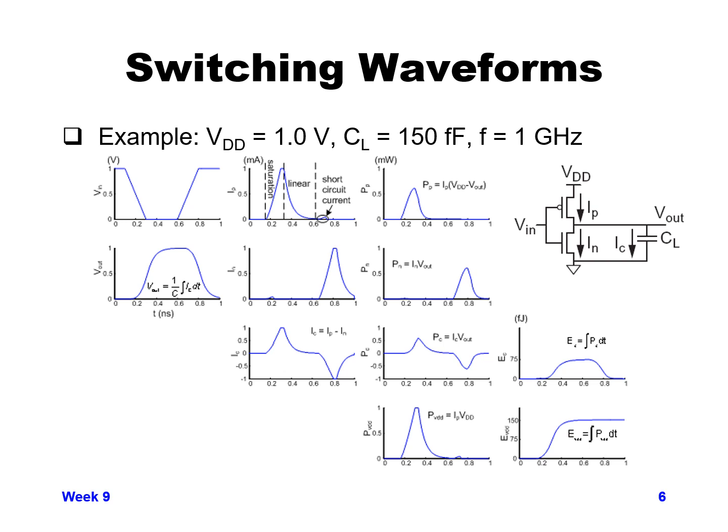So if you didn't fully understand all of that, you can go through this slide again, but make sure that this is showing how all of your energy is consumed by charging the capacitor, but half of it goes to just the PMOS device dissipation, half of it actually gets stored in the capacitor, and then you can discharge the capacitor and effectively dissipate the rest of that energy in the NMOS device when you discharge the capacitor.